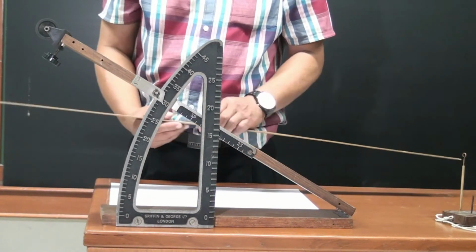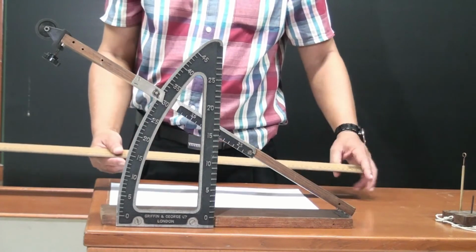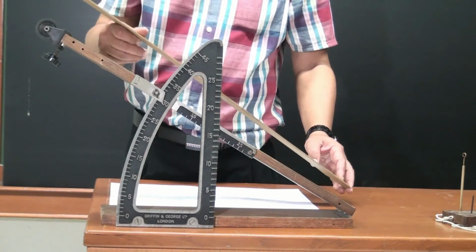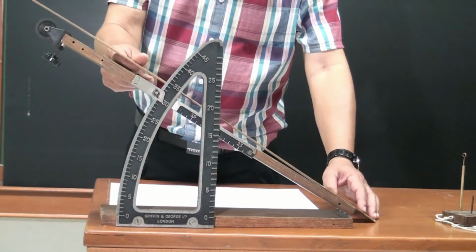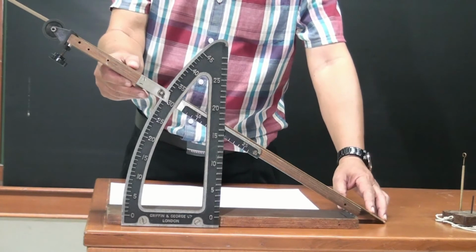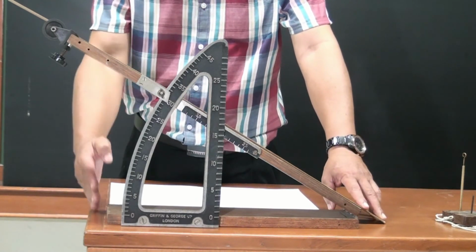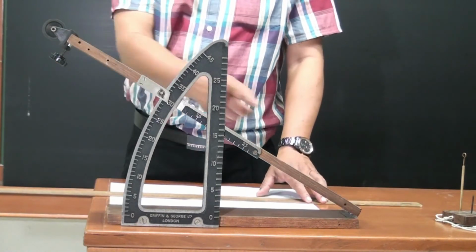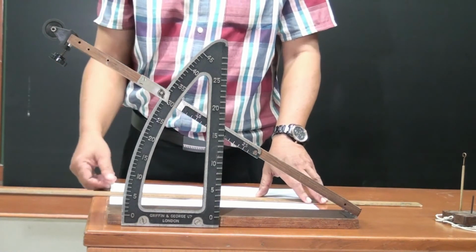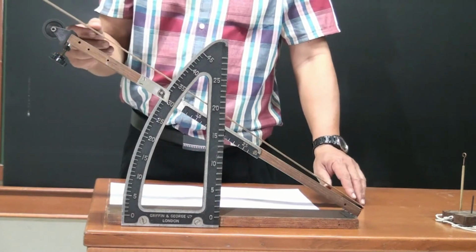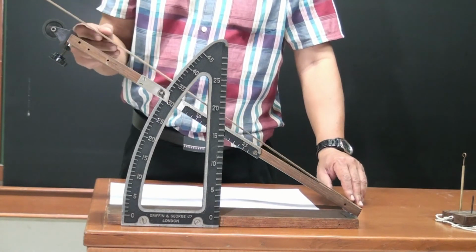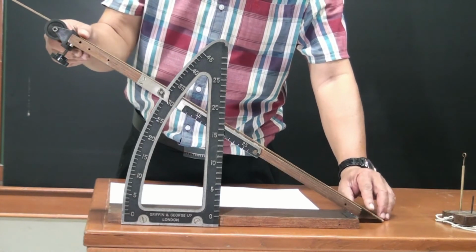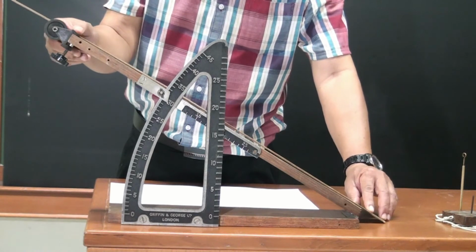So to get the distance s, you want to make sure that you measure the length from the bottom all the way up. This is going to give you a proper measurement of the distance s, and the vertical height is going to be your y. So be sure to get both s and y, the vertical axis and the inclination axis. Record your s, record your y, and then put s over y to calculate the velocity ratio.